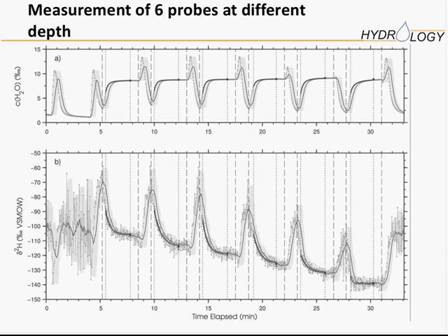In this case, we were around 7,000 ppm, and you can also see that the deuterium values are then stabilizing to certain values, and we can then use that together with the temperature measurements to back calculate the liquid water in the soil.